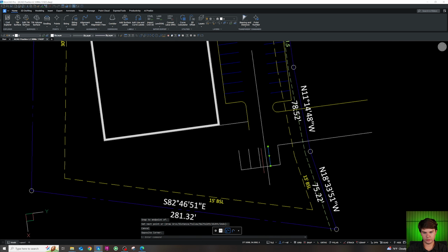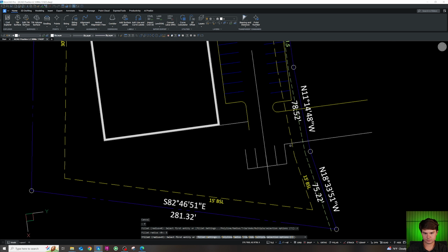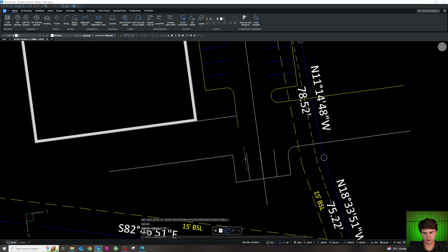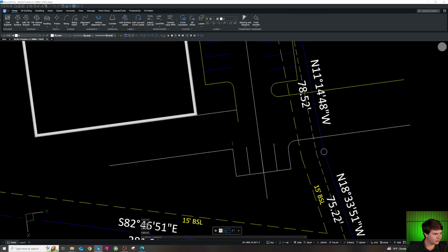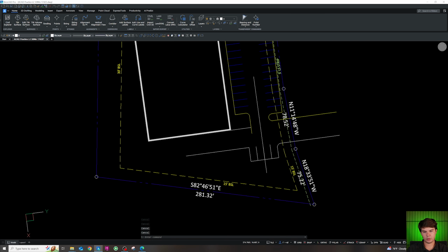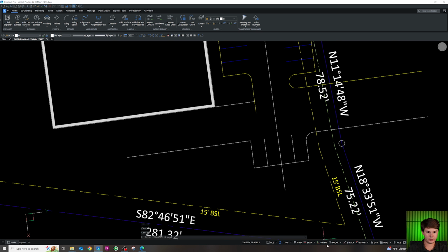Now I'm going to move these to center with this line, and we're gonna put it right here. Now that this is centered, you can connect it like that and give it a radius. That a 4-foot radius, and now our dumpster looks like it's about 45-degree angle, so we'll go down to our polar and check 45 degrees, come down from here.